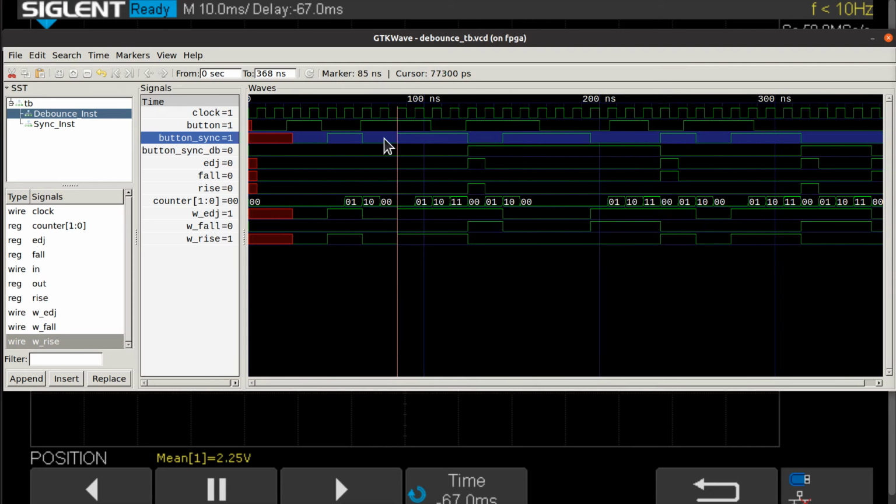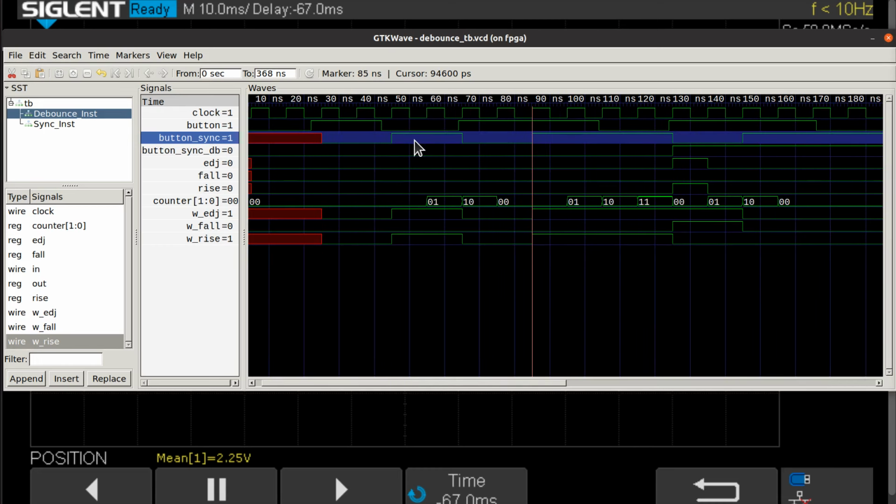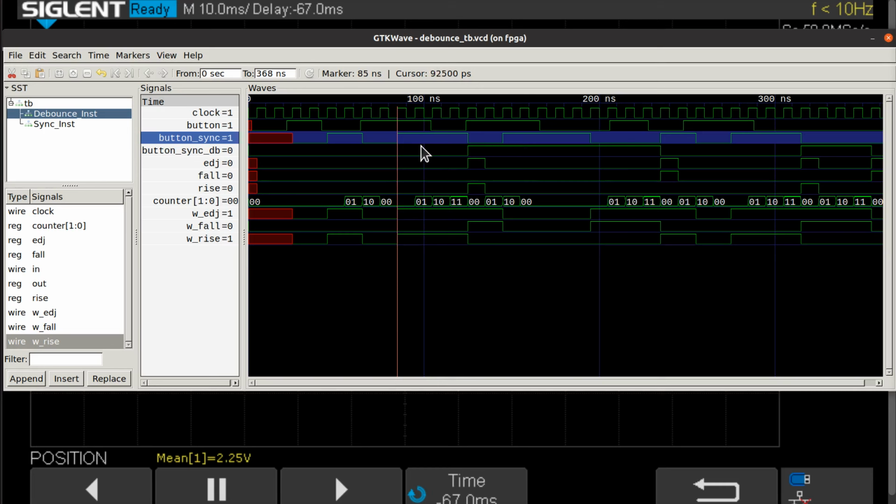Now, this particular simulation doesn't show propagation delays. Fancier ones do, and I think this one can if we get really cute about it and tell it this has a 5 nanosecond propagation delay, and you zoom in a lot and you'd see this goes up, then the one down there would go up as a response to that. Or there'd be a cause-effect arrow in here if you drew this out in a diagram, for a data sheet or something like that. Point is, you're looking at just to the left of the rising edge to see what this thing is and what it means to the circuit. So it's 0 again, so this thing stays 0 is my point.